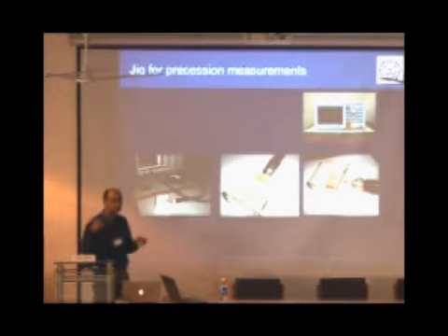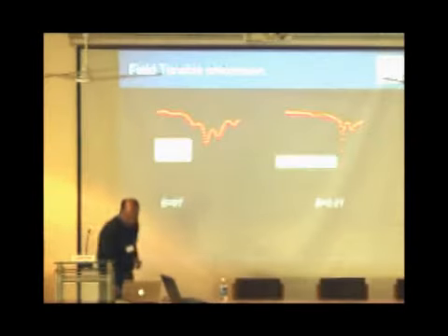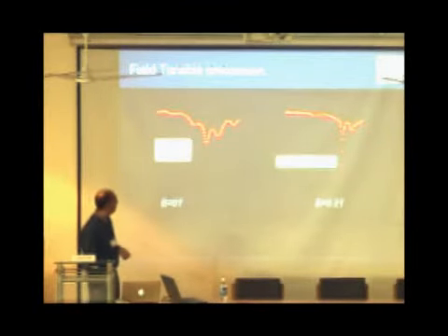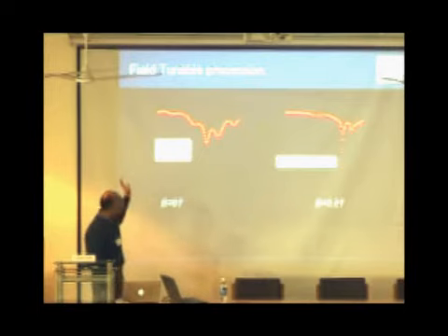What it does is it essentially launches a pulse of an electromagnetic field along the transmission line. When it comes close, the bow tie acts as a near field antenna, focuses the wave and causes a very sharp magnetic field to be applied right where you put the sample. So if you do that and then you sweep the frequency, what you get is an absorption curve over a certain band. Sorry, I used black again here.